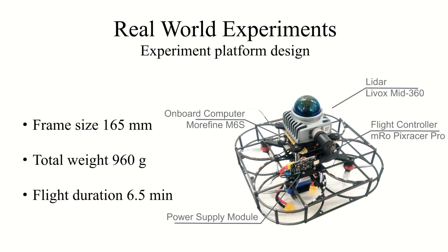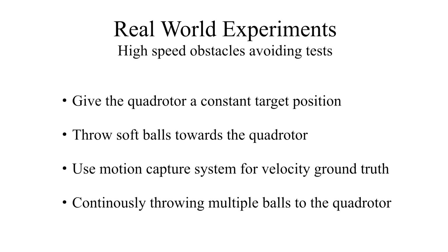We also present real-world experiments to verify the effectiveness of our approach. We designed an experiment platform at the size of 165 millimeters. It weighs 960 grams with all the equipment like onboard computer and lidar, and its flight duration could reach 6.5 minutes. In the first experiment, we test our system's ability of avoiding high-speed obstacles.